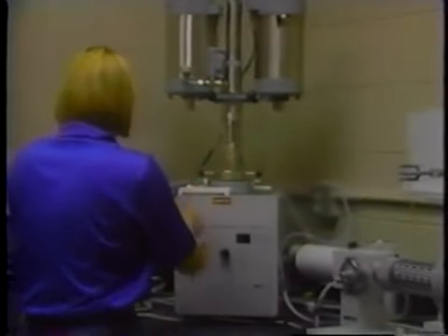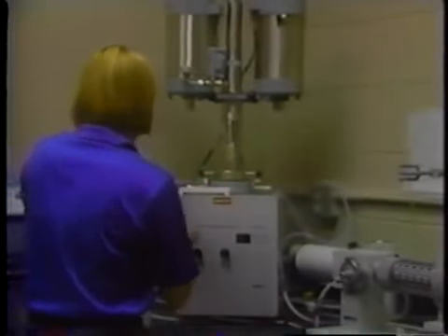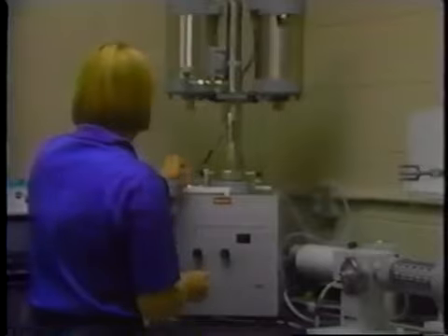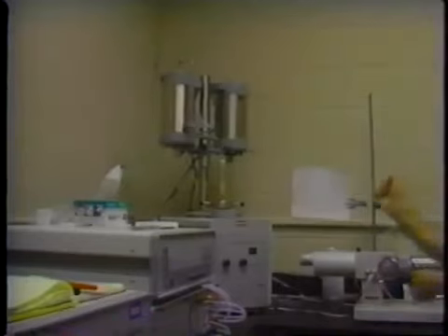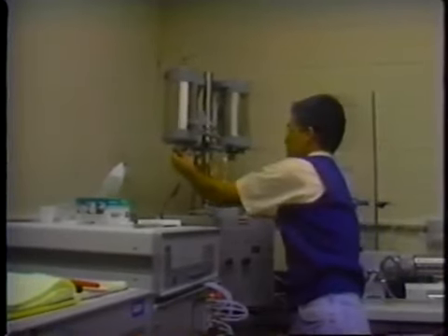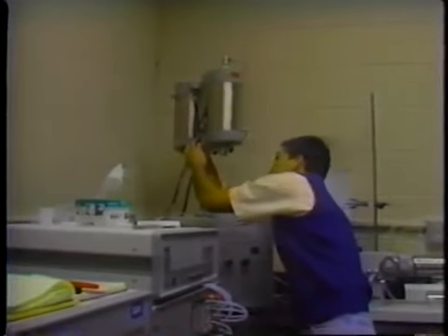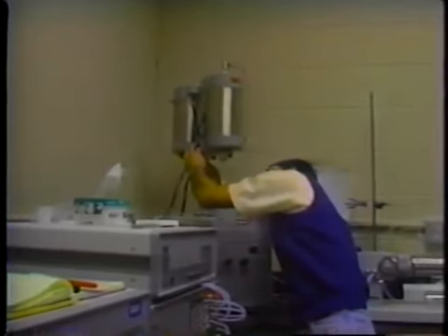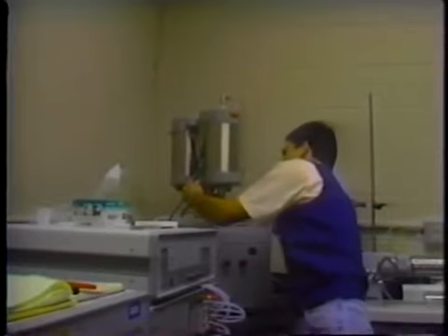Scientists are using measurements of other properties to monitor concrete setting and hardening. Researchers often need to know what portion of the cement has hydrated. The degree of hydration can be estimated by heating a sample of cement paste and measuring weight loss as a function of temperature using thermogravimetric analysis equipment.